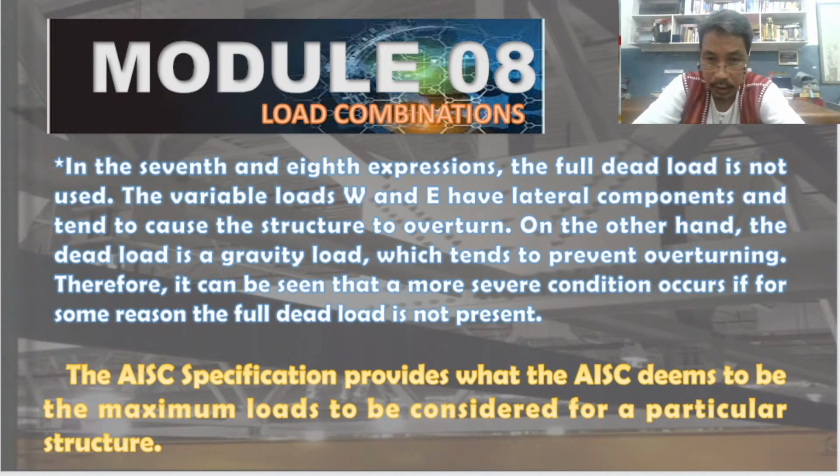Therefore, a more severe condition occurs if for some reason full dead load is not present, since the gravity load would negate the harmful effect of wind and earthquake.